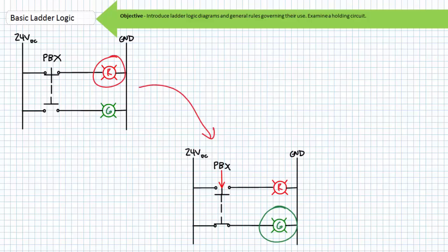When an operator presses the single push button for the mechanically interlocked break-make push button package, the normally closed contact opens and the normally open contact closes at the push of a single button. The red light turns off and the green light comes on. This subtle modification, the inclusion of a mechanically interlocked push button package, has fundamentally changed the behavior of this electrically controlled system.